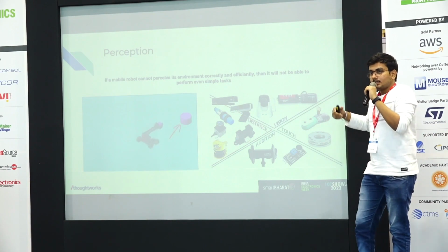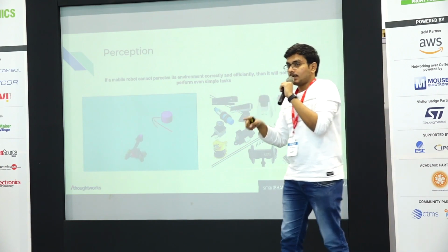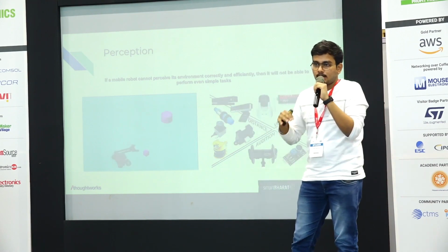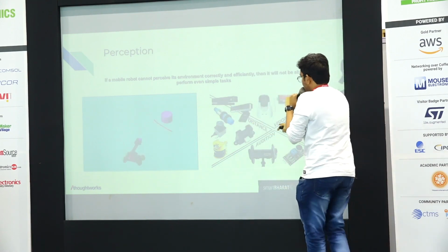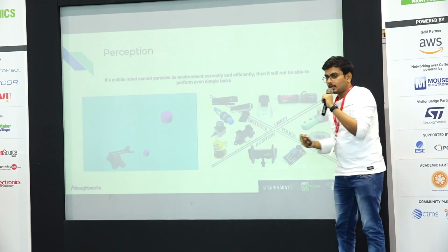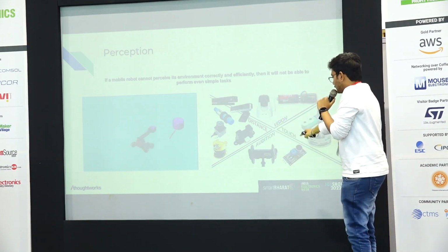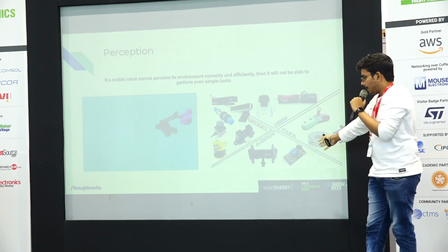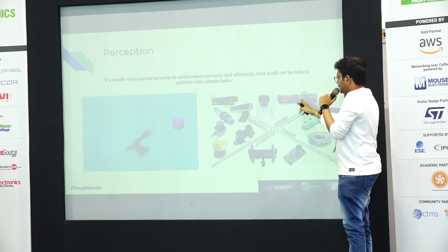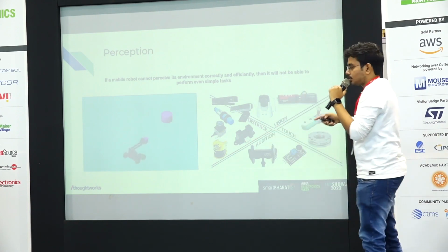We can select these sensors depending on our requirements. For example, in this kind of exhibition space, there will be multiple crowds running, so we cannot just go with a single sensor. We need to add multiple sensors so that we can error correct. For example, among the distance sensors, you have the depth camera, LiDAR, IR sensor, and wheel encoders. These give the distance of the object, or the distance the robot has traveled so far. There are also audio-based sensors like a microphone, touch sensors, magnet and Hall effect sensors, and for vision, a camera and an auto vision camera. So these are the different sensors used for the perception stack.